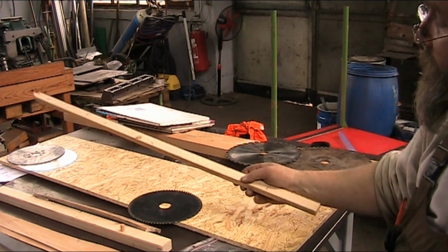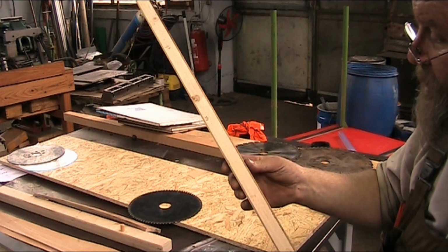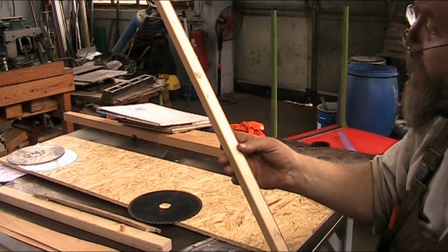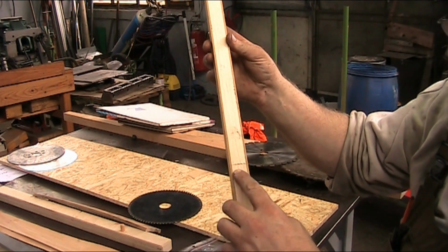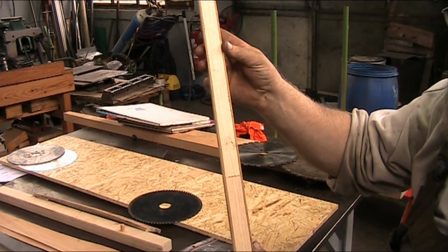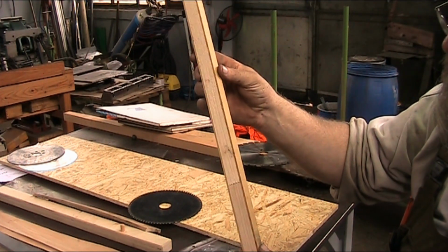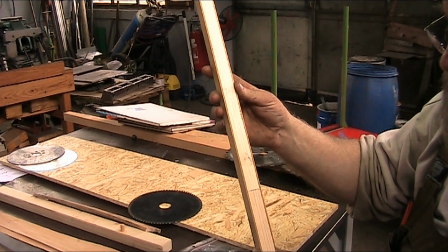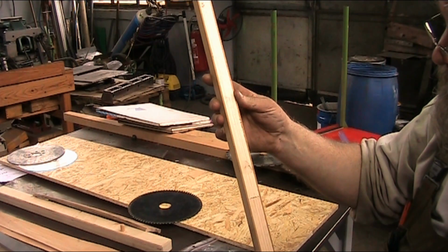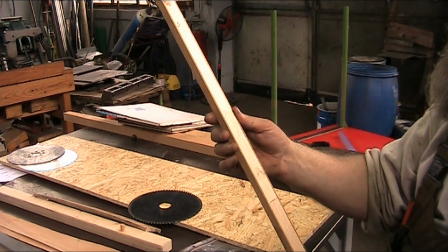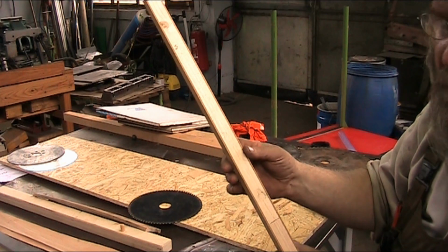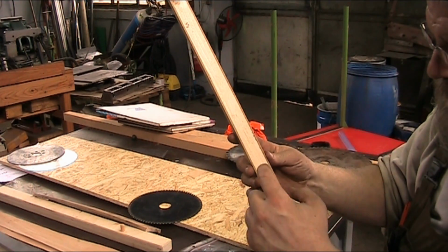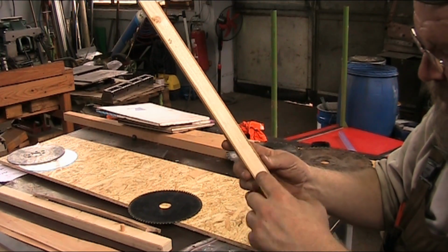So then there's also this other engineered product. This is a sandwich board, and you have a solid wood core that's sometimes been finger jointed. You can see the joint right here, and then it has MDF covering. Sometimes they'll have an OSB core with a veneered coating on top of it. That's also a product I've used in the past, and I'm not real thrilled about it because when you run a screw into it, it has a tendency to split, especially if you're running a screw into the face end of the board.